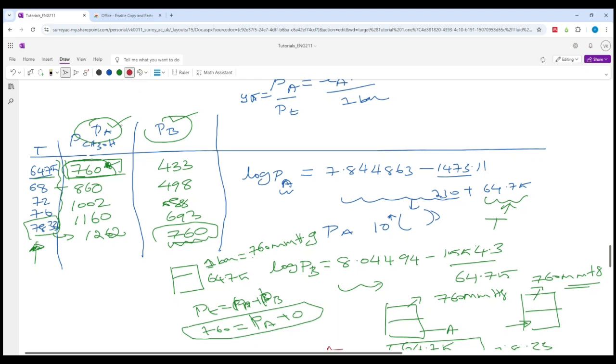So follow the red color ink. So we have here vapor pressure of A, vapor pressure of B. From here we can calculate the alpha value, which is nothing but PA by PB. I already calculated this value, so I can enter them. Later you can check 1.755, 1.727, and this I see already some interesting numbers there, and 1.674, and then 1.661.